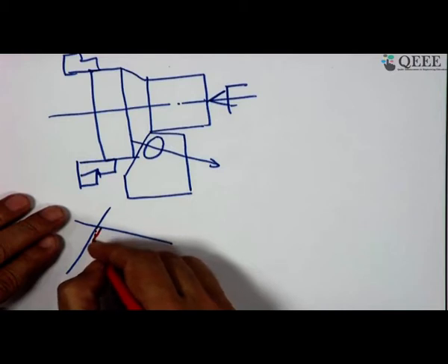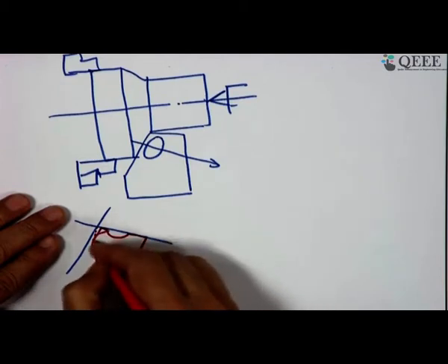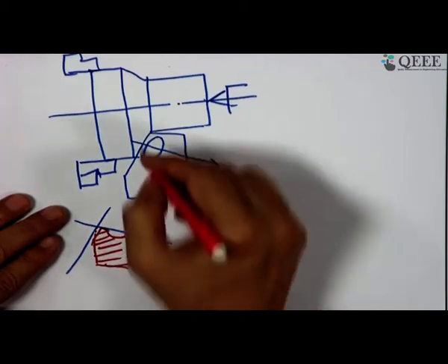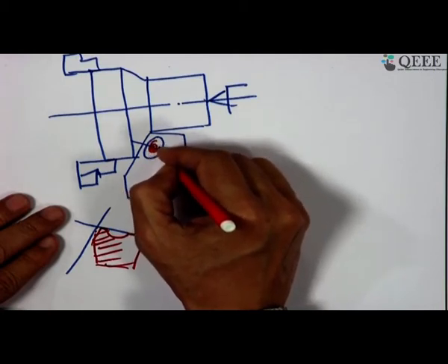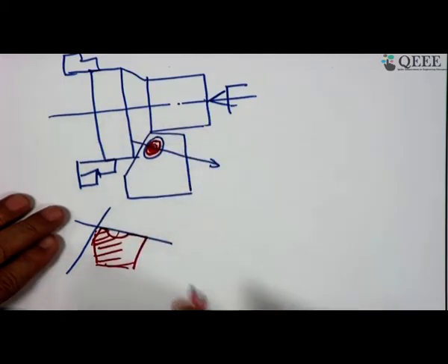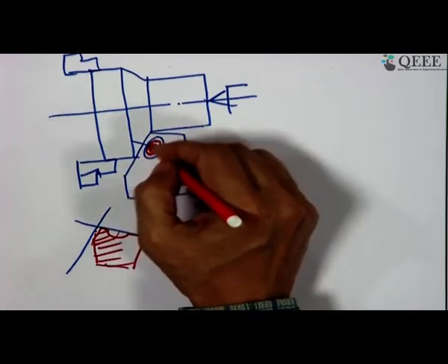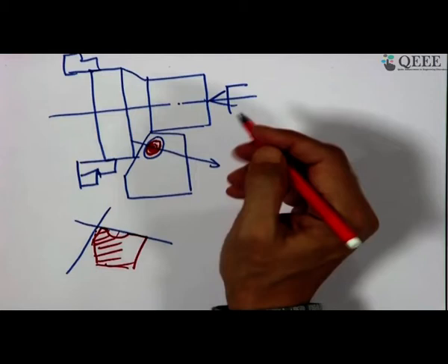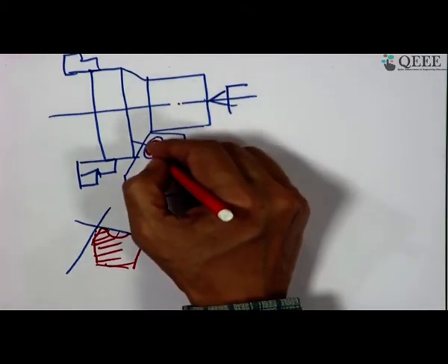So, this is now the flank wear, it is worn out, and this is the land and this is the tool. So, that will be the cross section, and it starts here and it grows. It grows in width in both dimensions, and it depends. So, the depth is increasing, the width is increasing. Now, when this width keeps on increasing, the crater has two edges, two frontiers. One is the trailing edge, another is the leading edge.